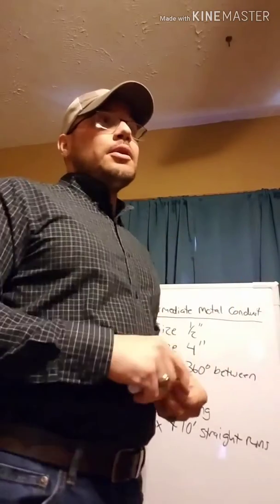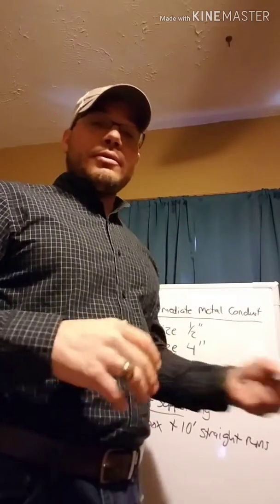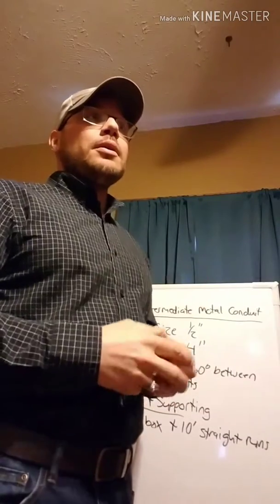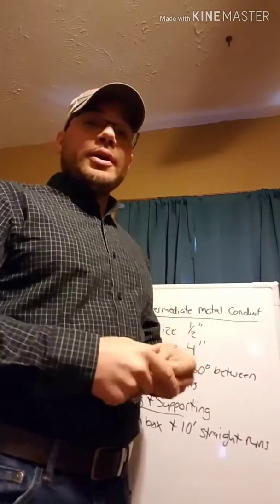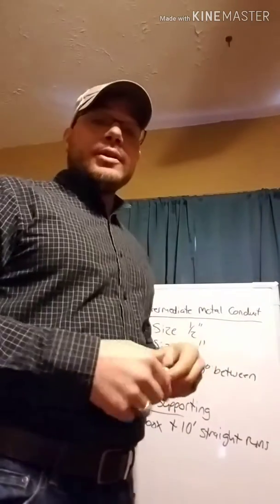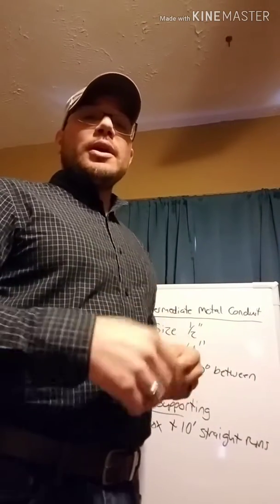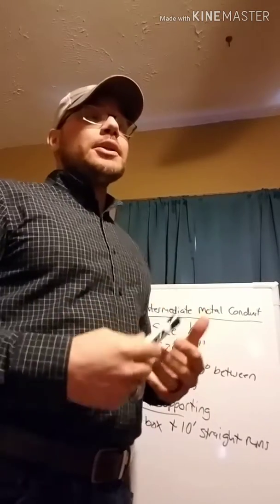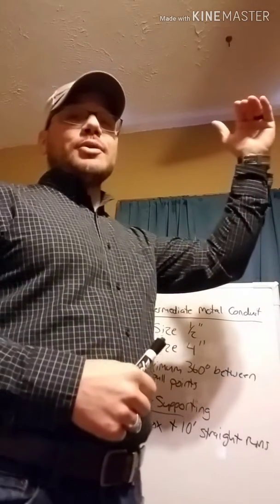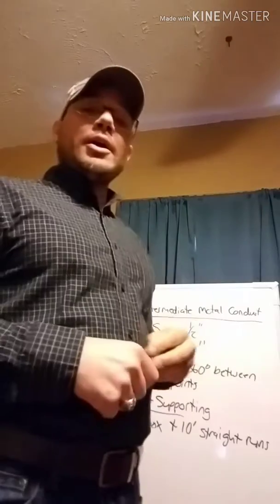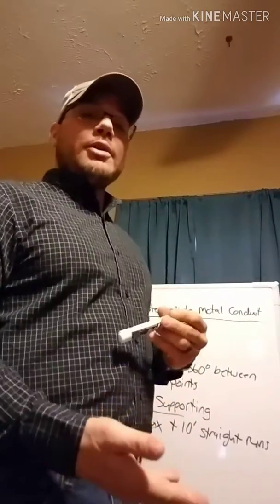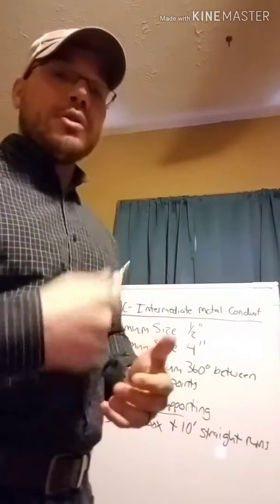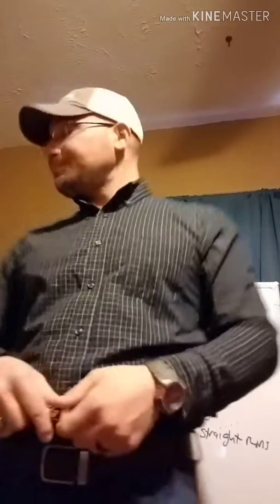Next time you're in school, whenever that ends up being, if you look in our machine tool area going down to their machines, you'll see that we have some of those drops, but we actually use flex for it for the most part. But the biggest thing is make sure it's securely supported at the top so it's not pulling down on that conduit, and securely supported at the bottom so that it's holding it up, so it's not pushing into that machine. Okay, so we'll go up to 20 feet there.